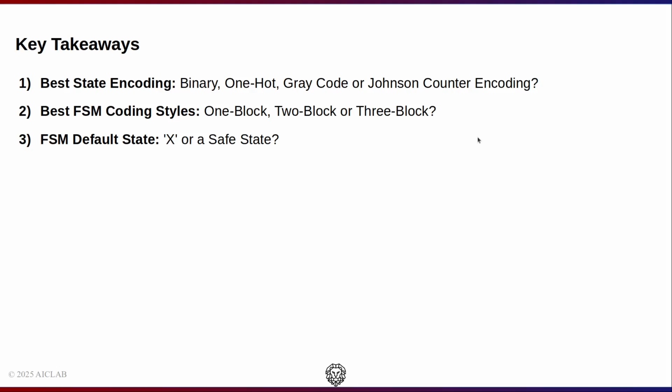What is the best FSM coding style? 1 block, 2 block, or 3 block? The answer is that there is no best solution. Based on your personal preference, the team you are working with, and the design, choose the best one. What should we do for FSM default statement? X value or safe state? My recommendation is to use a safe state. In rare cases where you are limited by area or your timing is tight, you can use X value. In this case, the synthesis tools generate a more optimized circuit.